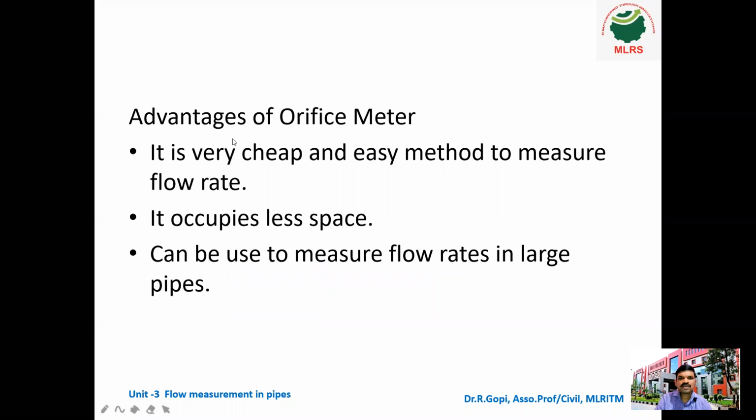The advantages we have already seen. It is a very cheap and easy method to measure the rate of flow in a pipe. It occupies very little space and can be used to measure the rate of flow in large pipes. These are the three major advantages. Sometimes they will ask in a 2 mark question: what are the advantages of the orifice meter compared to the Venturi meter?